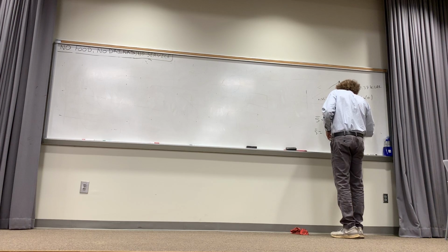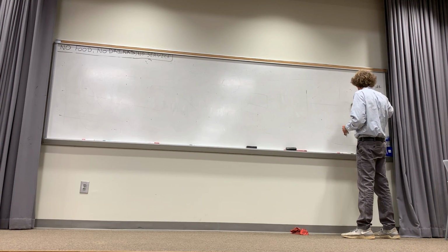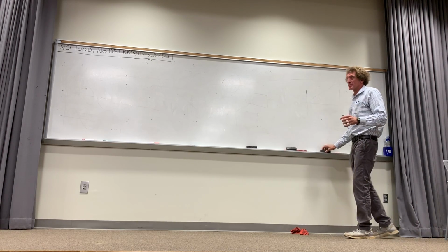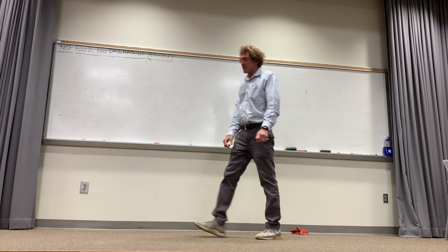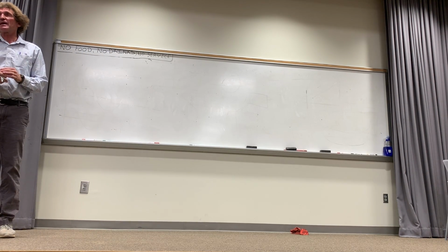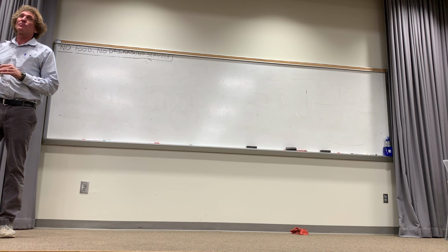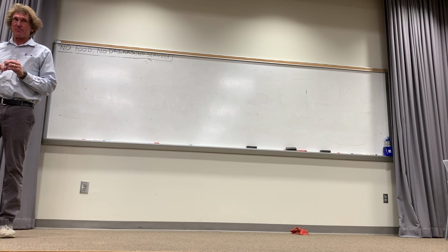Now, I want to tell you this over and over again. This is our motivation. We do not want any kind of reactive power in the circuit if we can help it. We'd like to take it and zero it out. So what we're going to do is add an element that will add, quote, negative reactive power.